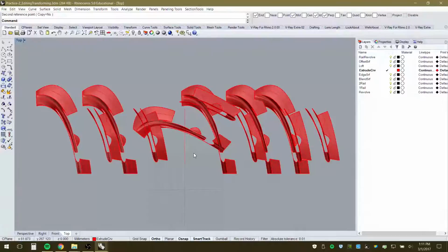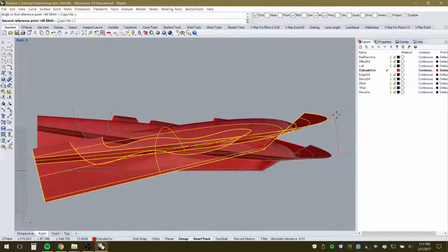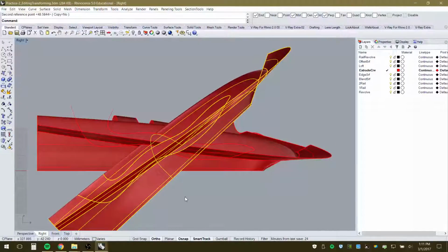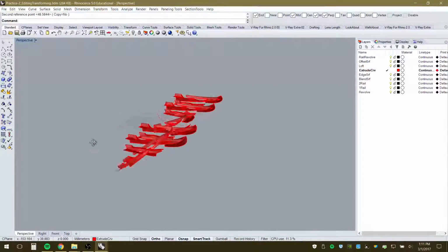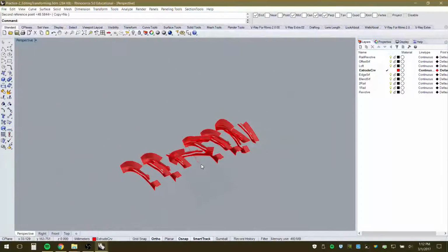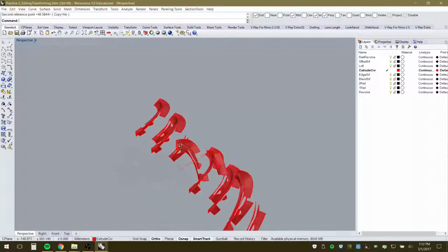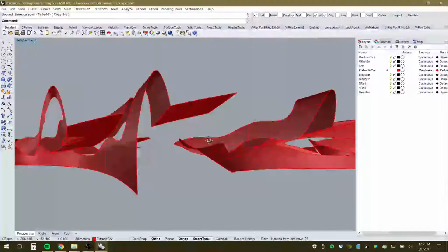But it's about the Z-axis in this case, and depending on the view, it's going to be about, if I select this and right-click to re-execute the last command, now this is going to be about X or Y, whatever this view might be. It's the right view, so I guess it would be X. So that can be limiting, depending on how you want it to rotate. It's fairly absolute about the orthographic orientation of things. Let's say I wanted to rotate something about this axis, whatever this might be, this line right here. And that's what I needed to rotate. And so you can do that.